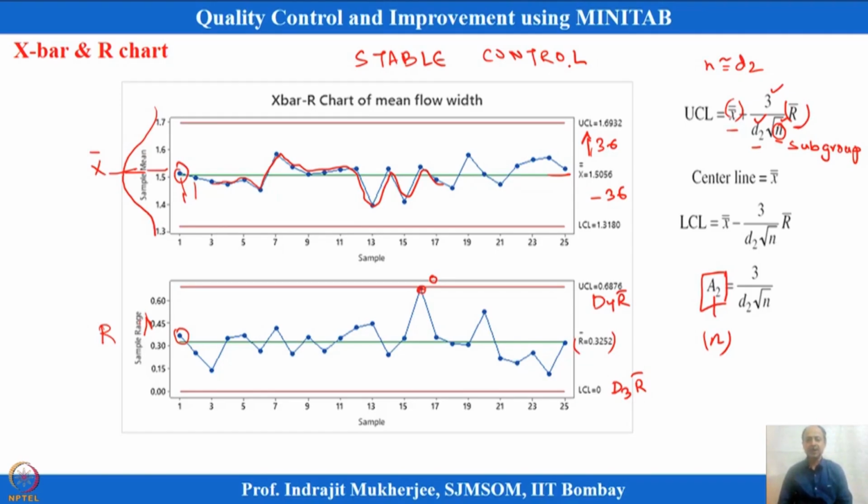Even if there is variation within this, what the control chart says is that there will be variation in the process, but do not unnecessarily adjust the process. It is unnecessary because variation is natural over here, and within plus or minus 3 standard deviations, that is completely natural. So, point to point variation will be there. Do not take action when it is within the control limit line. Over adjustment is to be avoided. Okay. So, over adjustment is unnecessary. So, that is the idea of control charting.